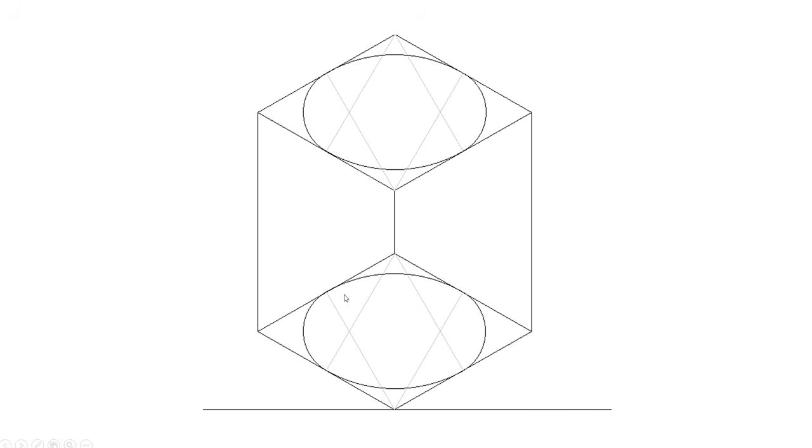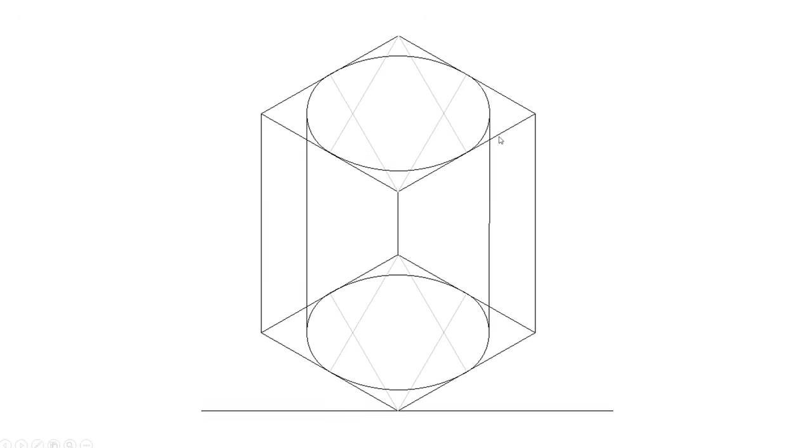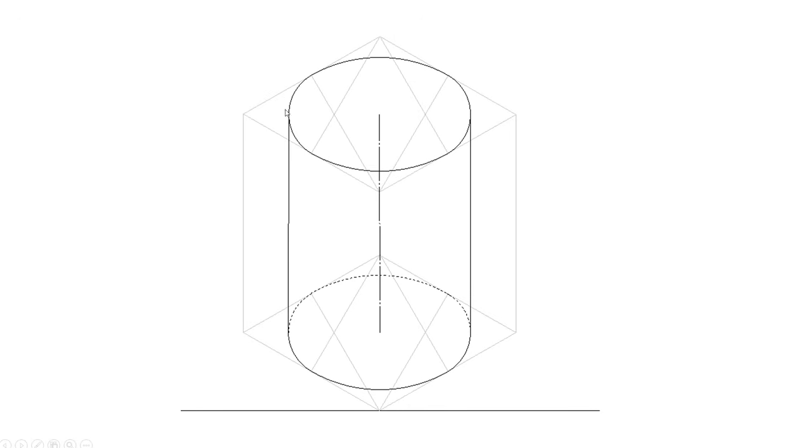Now once you draw that, you want to draw a line tangent to this curve. These two are ellipses. So from this ellipse to this ellipse, you want to draw a line tangent from here to here. Now similarly this side also you draw a tangent line like this. And now in this case the portion which is coming inside, so this is the base, this portion will be invisible because whatever is coming inside of this tangent and this base curve, this portion will be dotted line. So you want to make those lines as dotted lines.